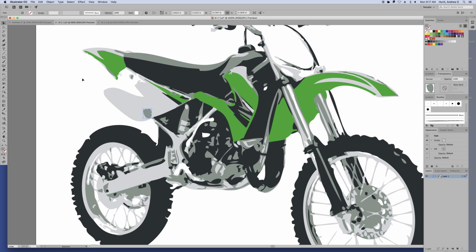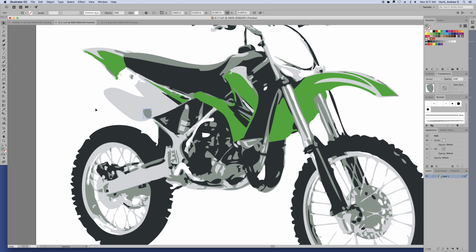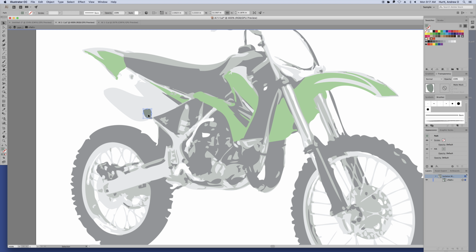So the isolation mode thing, again, let's say you just wanted to work on this piece by itself without accidentally selecting. So now we can't select any of this by accident. I'm dragging to select and it won't let me. This is one that I do all the time by accident. I'm going to hit escape to get out of it, but I'll go to click something and I'll just accidentally double click, and then you see how it grays out, sort of washes out all the other objects.